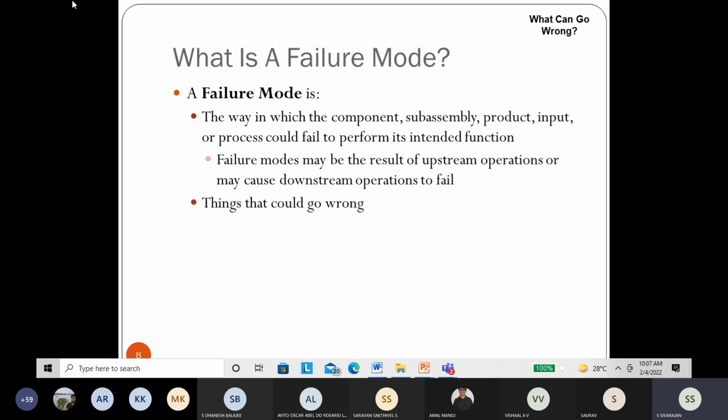But manually, when we are working on the milling machine or the drilling machine, many times an oversized hole will come, because the operator also influences. But on a CNC machine, the oversized hole will not be a problem. Okay, sir. So it's mainly human error also, all those factors. Yes, yes. When you are working on a drilling machine, the machine will vibrate many times, because CNC machines' rigidity is very good. They will not vibrate. But they are expensive. That is the problem.